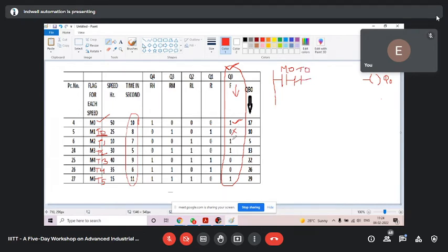Now, again it is on, you see Q0, only Q0 you see. Again Q0 is on. When it is on again, what is the signal? T1, next timer. So T1 will make it on. For on you have to take NO in parallel. Correct? Next. Consecutive on you have to skip, because once T1 is on it will continue on. No need to take T2 also in parallel. Okay, these two have been done.